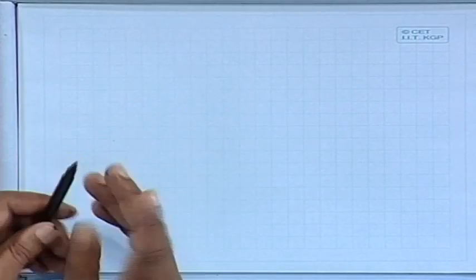It is much more than that, where you have to provide the minimum reinforcement that you have to follow. So, what was our motive actually for checking two sections? Initially I have taken 250 by 300 and I have used 4 number 12 bars, just arbitrarily. Then even then I am coming to 250 by 250.